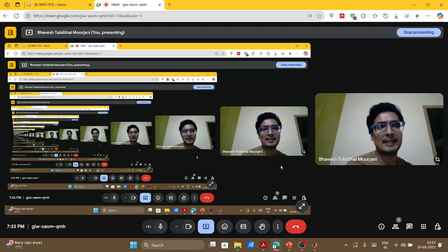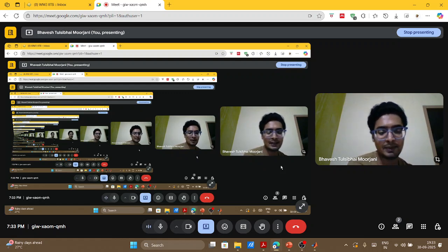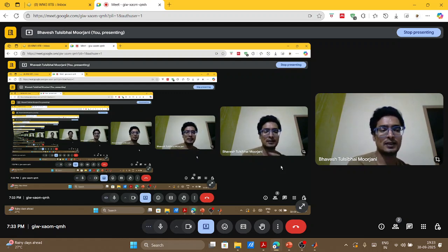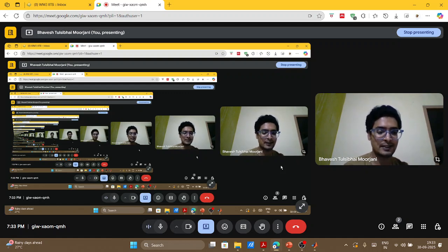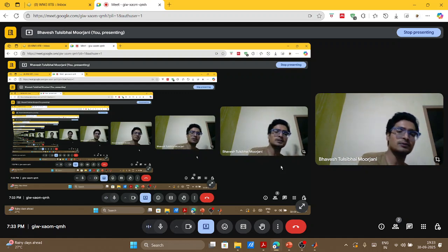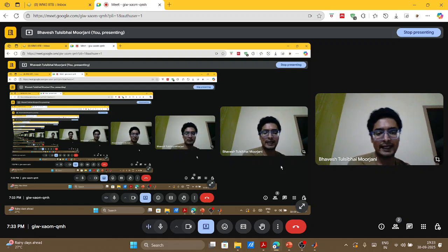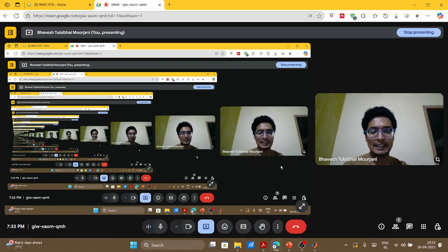Now where will be that case? If you recall the previous class where we had done the 2D fin problem, in that class we were doing the time evolution of the temperature profiles, right? With the time, the base of the fin was subjected to the heat generation, and that heat generation was time dependent. Because of that, the temperature profile was changing at the bottom, and obviously because of the conduction and the convection, the overall temperature profile of your fin was changing, right?